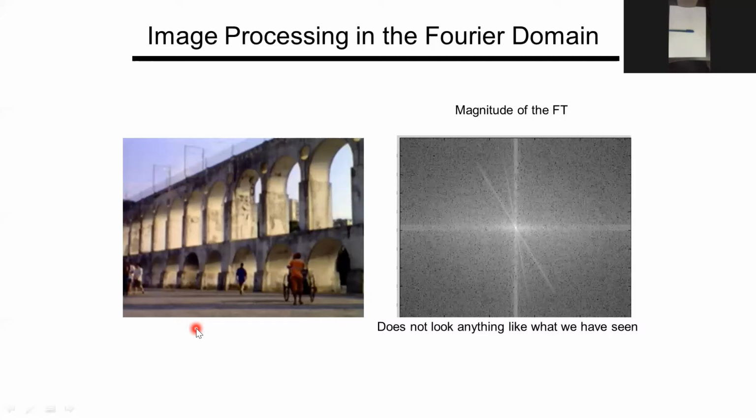The second issue is related to the multidimensional Fourier transform. When we are dealing with time to frequency, it's a single dimension to a single dimension. Time is a single dimension and the frequency is a single dimension. See? So it's a direct correlation. However, in two-dimensional image processing, we are doing a 2D Fourier transform, because you have a two-dimensional image. So we are now interested in converting this two-dimensional spatial domain into a frequency domain, which is another interesting and challenging point, by the way.